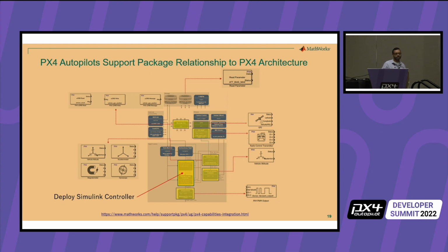There's good documentation on it, but we take off both these controllers, and then we directly deploy a Simulink app that can read the current state and push in your own specific controller. Maybe you have a different mixer, or your drone's not just a standard quadcopter, it has tilt and pitch for each of its arms. So the control scheme's not just going to be the standard position rate controller. So that's what I'm going to go over today.